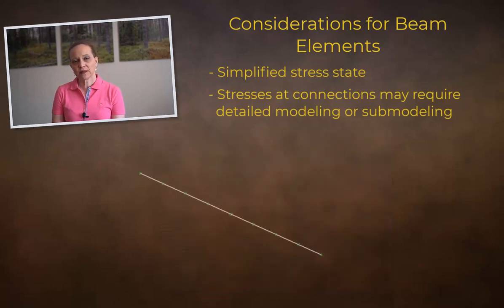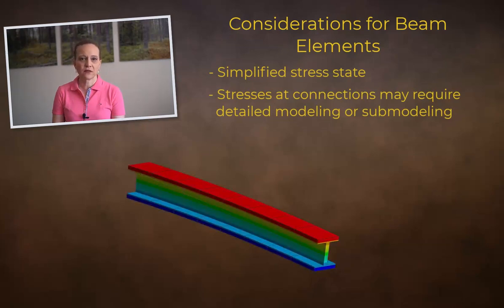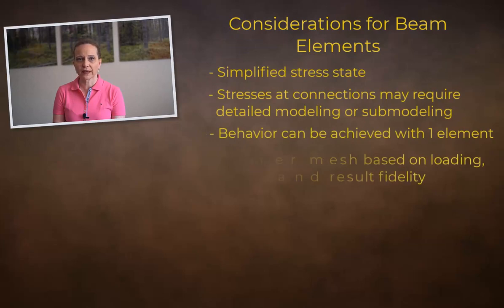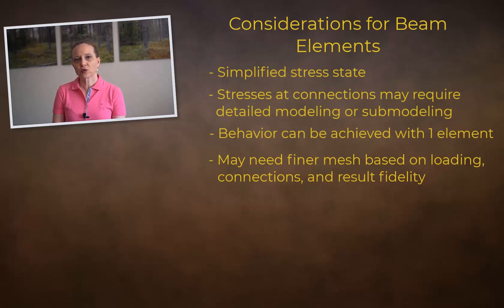While the beam element is 1D, the cross-sectional information is stored and calculated to allow for 3D visualization, greatly facilitating results interpretation. Keep in mind that we can represent the beam behavior with just a single element, but adding more nodes along the length may be necessary or desirable if we wish to more accurately visualize results along the beam, for example, with a shear moment diagram or results at a specific location along the beam. We may also need more elements to interface with other parts at specific locations, or even where point loads and moments will be specified.